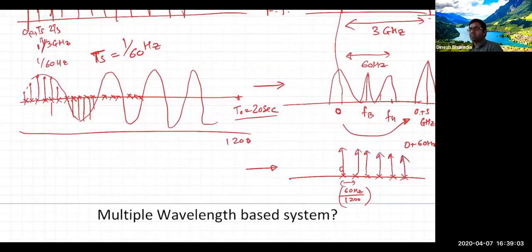Right, everyone with me? Up to, all the way up to minus infinity to plus infinity, okay? The separation between these two bins is 60 hertz over 1200, roughly 0.05, okay? This is an impulse train here. What I'm going to do is multiply in this domain, which leads to convolution. What happens with this kind of impulse train, guys?